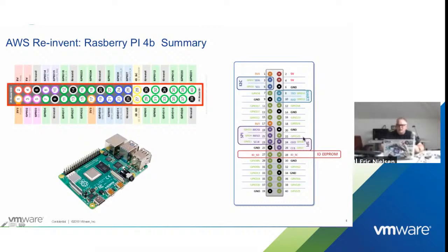There is also an SPI bus line. SPI is a very common protocol to talk to sensors. So they have a clock, and CE0 and CE1 is basically an individual line for each sensor, and you can only run 1 sensor per line. So it's a bus, but it's not really a bus. But you have clock and data there, and so you got that. So that's another set of pins, 19, 21, 23, 24, and 26.